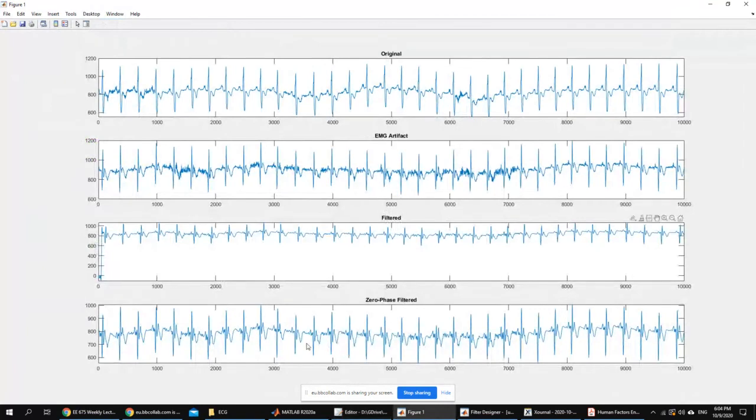So you get a different signal here, and a different response here. Sometimes it's good to look at another signal, because for one particular signal, it's okay to use a filter with particular specifications, but if you try it on another signal, it might look really bad, like this one here. It's exactly the same parameters, but it looks much worse.